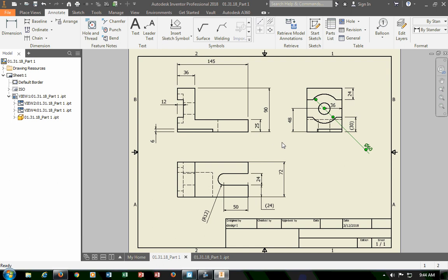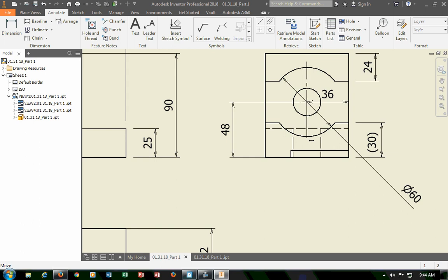We're missing center lines, right? Center marks. So center marks are right there. All you've got to do is pick the object and your center marks appear. So it's pretty straightforward. You will want to extend them out. Some of these dimensions you'll want to pull out to be attached to those end marks instead. If you built it like an arc, I think this thing was built like an arc, this particular object. The top arc, I think there were arcs, so I'm going to pick the center object instead because I'm going to try to get center lines. Let's see if I get, there we go. I'd rather get center lines to be pulled out.